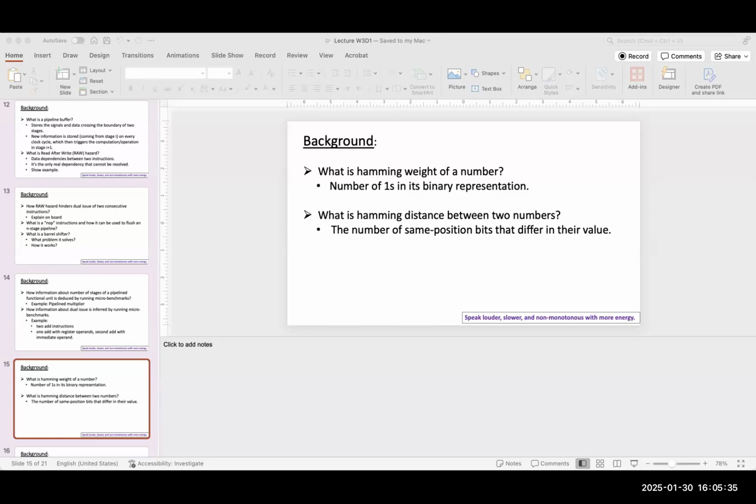Now by looking at the power which is consumed, by recording that power and looking at its trace, I can get information about what is happening in C, which gives me some information about the values of A and B, if I know the operation. How can I know the operation? By issuing an instruction OR C, A, B. I can control this, and I can look at the power consumption of this, right?